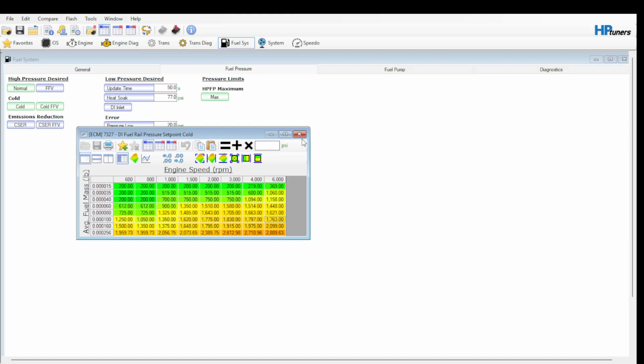So it's not smart to push them to 3,500 PSI. Don't get me wrong, but they'll work, and they'll keep working for apparently a very long time. And 3,000 is still, in my opinion, I would consider it safe. But at 3,000, they also lose a lot of their efficiency because the high pressure fuel pump itself loses volumetric efficiency as you go above that 2,200 PSI, right?